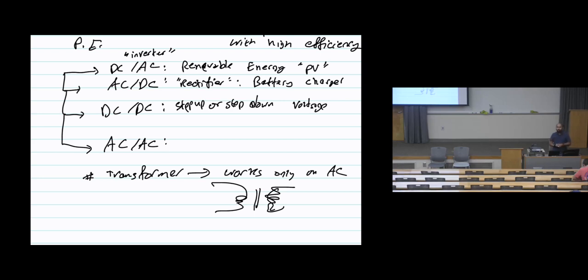It's not only about converting DC to DC. It can turn, for example, uncontrolled or unregulated DC into regulated DC. Say I have a DC source and I need to control a DC motor. The DC motor can be controlled based on the voltage. If you make the voltage high, the speed goes high; voltage low, speed goes low.